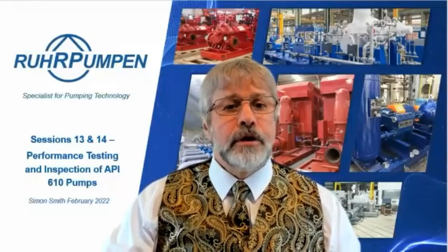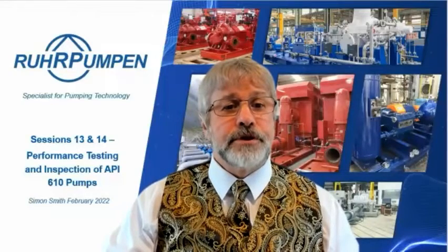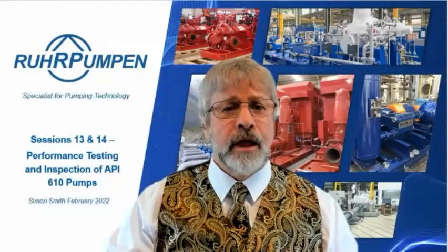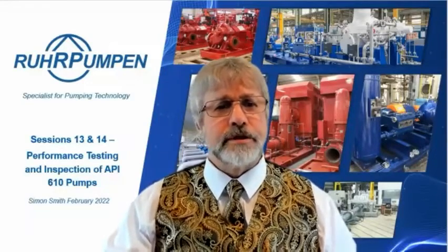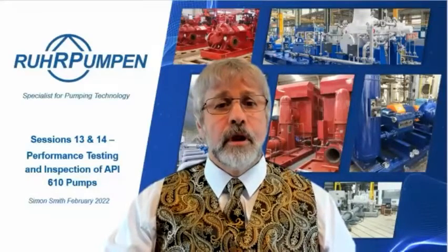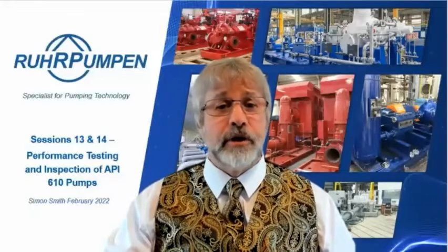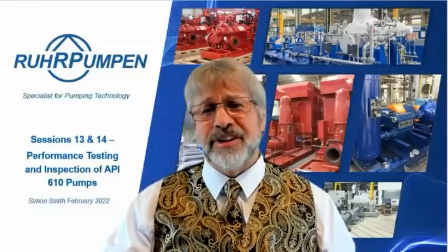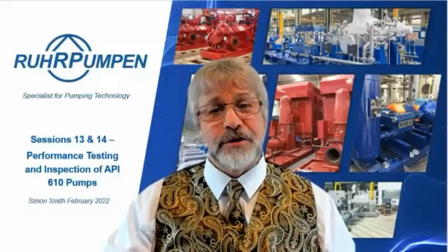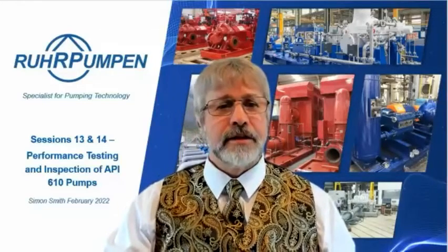Carlos Mallow, do you use the same acceptance criteria for vibration and temperatures for a complete unit test as for a performance test? I assume that's what you mean. Well, yeah, for vibration, yes, you'd be looking at the same vibration. Temperatures, you're testing on water, not on the process fluid. So bearing temperature, yes, you'd be looking at the same criteria.